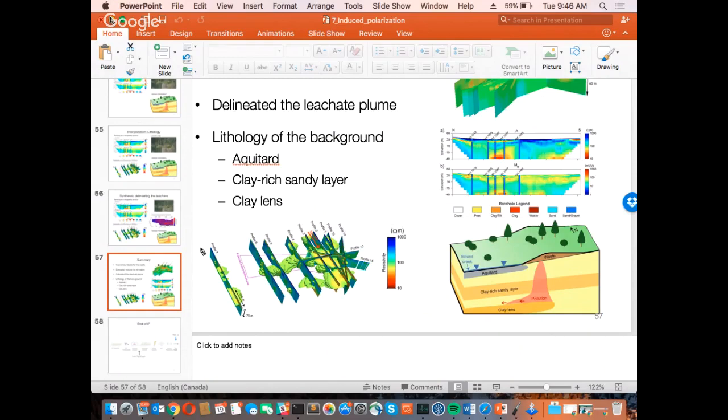Okay. Since you only really have power at those odd harmonics, you've got a particular frequency for your square wave that's going in. In order to get good information that you could compare in the frequency domain, you might have to do multiple time domain square waves, so you operate at different frequencies. I think a lot of people feel like they could do just one time domain measurement and get all of the frequencies. But in fact you really don't, because the power falls off.